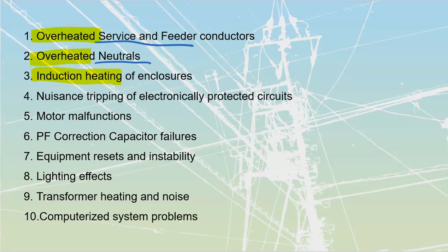Motors are going to malfunction. If we have motors that are affected by power quality, some of the big effects are decreased efficiency and decreased torque. You should remember we just went over the V/F, right? We are going to try to maintain a constant voltage-to-frequency ratio when we are speeding up a motor on a variable frequency drive.